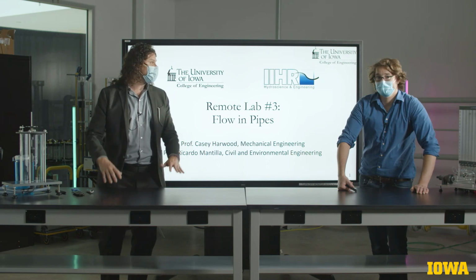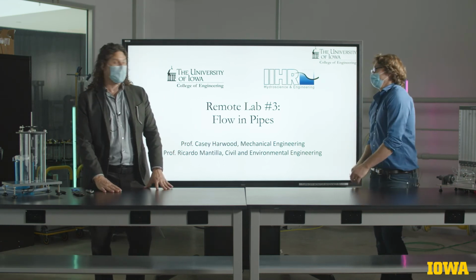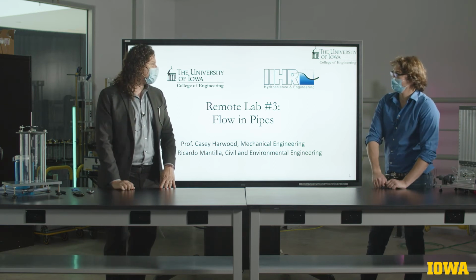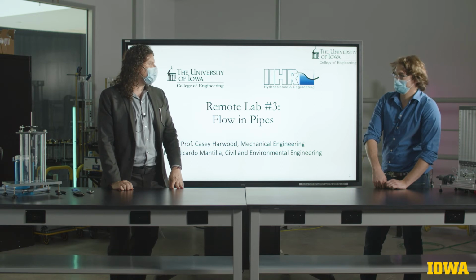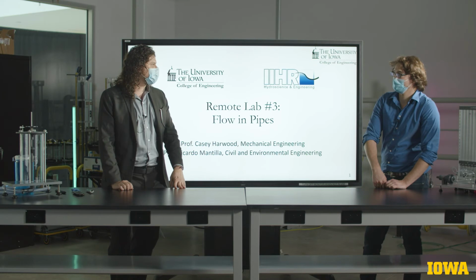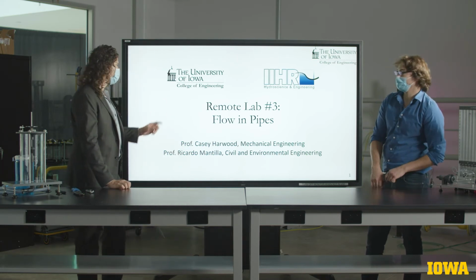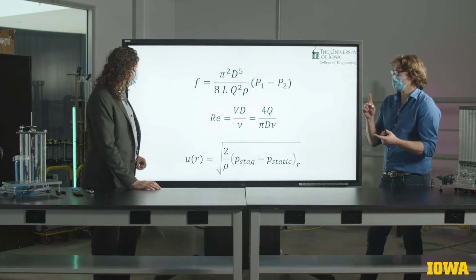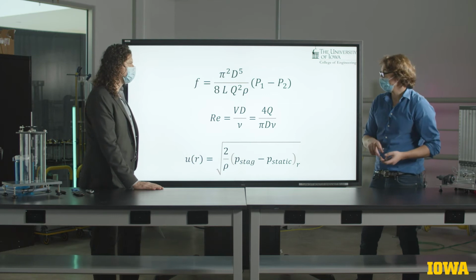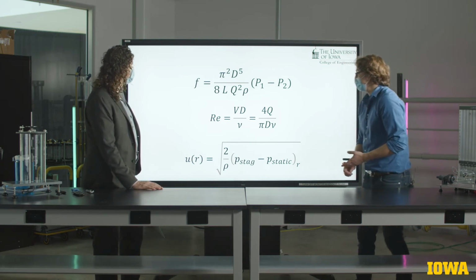Okay, so we're done with our measurements on the pipe experiment. So we measure differences in pressure, and we measure pressures using our pressure transducers, and we measure differences between the stagnation pressure and the static pressure to be able to determine velocities there. That's right. So we need to take another walk through how we turn those measured data into the volumetric flow rates, the friction factors, and the Reynolds numbers that we're interested in at the end of the day.